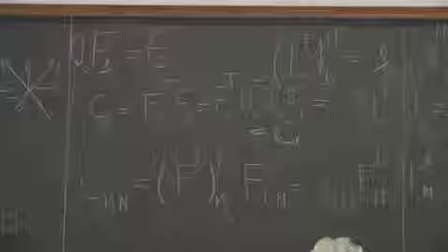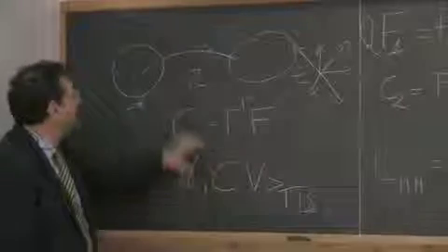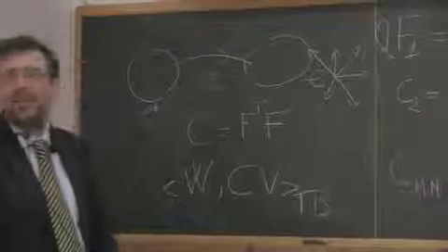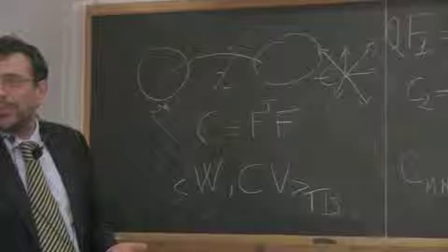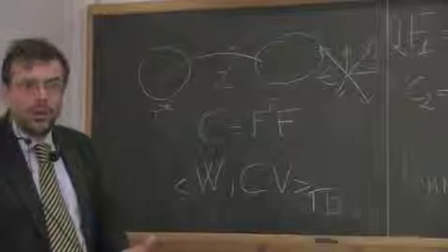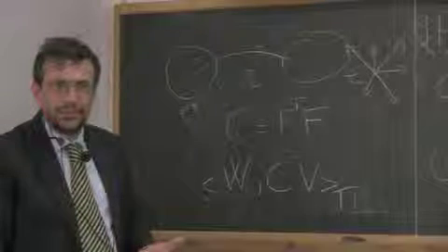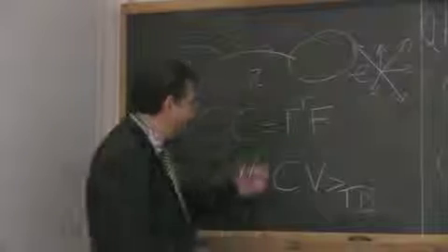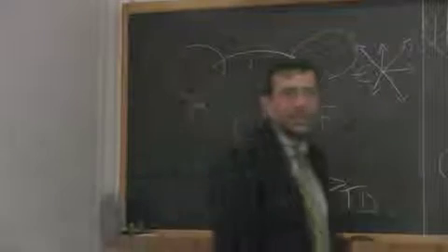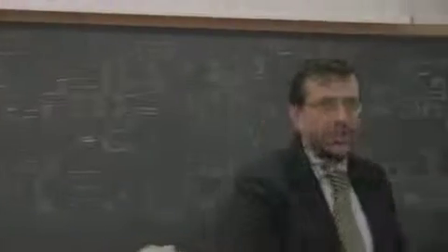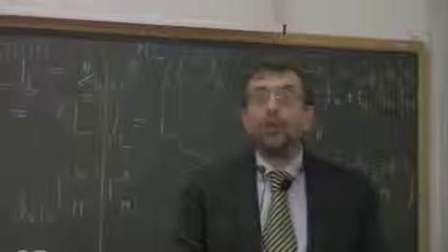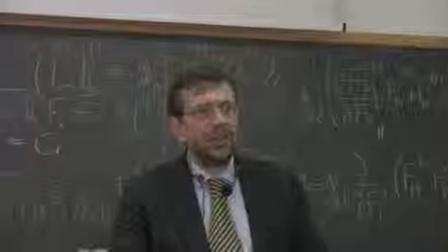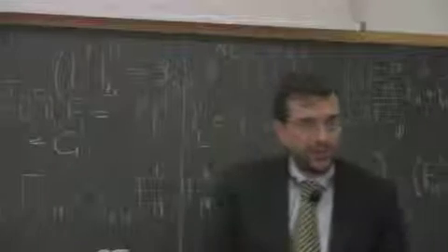So this quantity, this inner product in the Lagrangian configuration, is independent of the observer. Okay? So you have the tool for doing what you need. You will ask your deformation energy to depend on C. If your deformation energy depends on C only, then you are automatically assured that this deformation energy is independent of the observer.